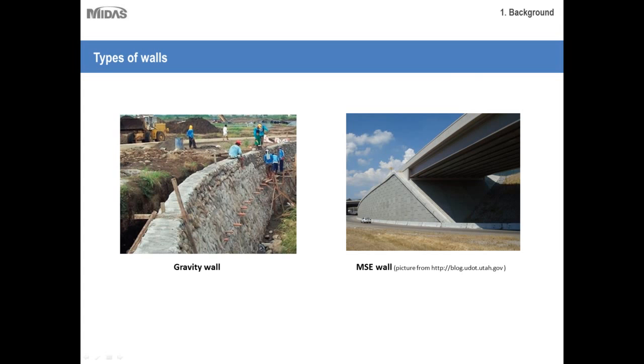It is called a gravity wall because they have their interiors either filled with gravel or soil, and they are massive structures. They are self-stabilized systems, and they are used at locations where there are no space limitations. But as you can see, they are not very aesthetic in appearance and have a crude finish.